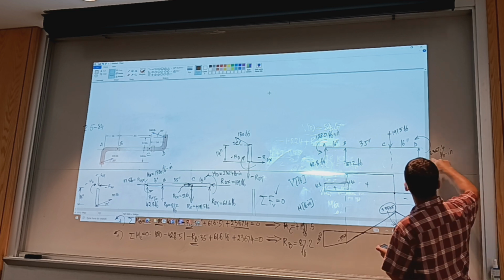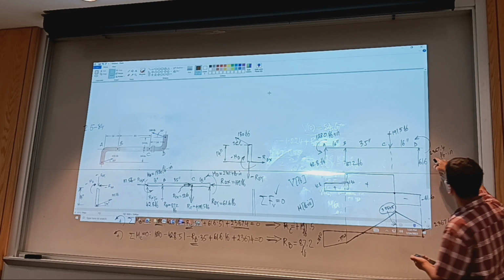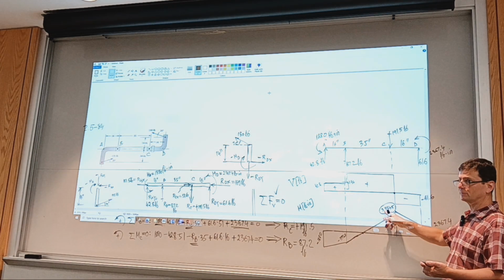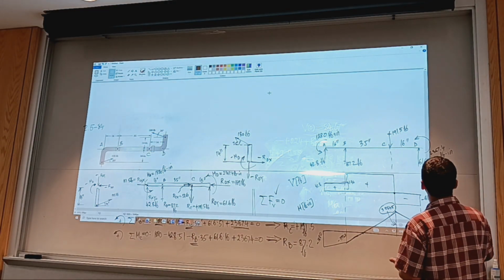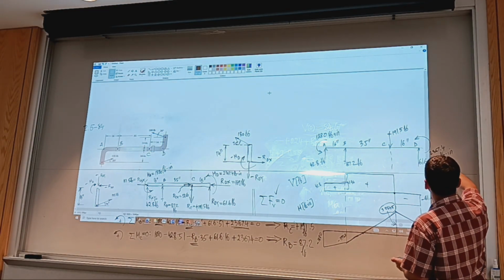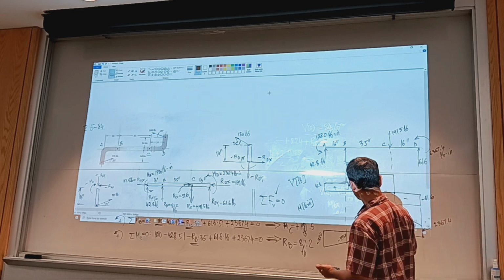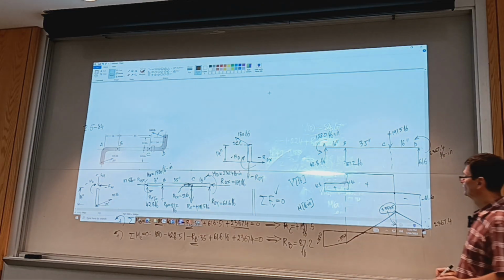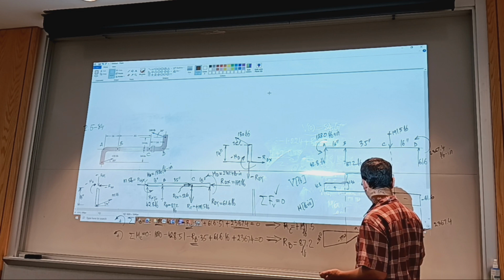And after point D, the diagram should close to 0. Due to this concentrated moment, the diagram will drop. It's counterclockwise. Is this value confirmed? The end value should be 2,367.4, or very close. If you want to know where the diagram goes to 0, we can use similar triangles. I can call this A, I can call this B, my preference.